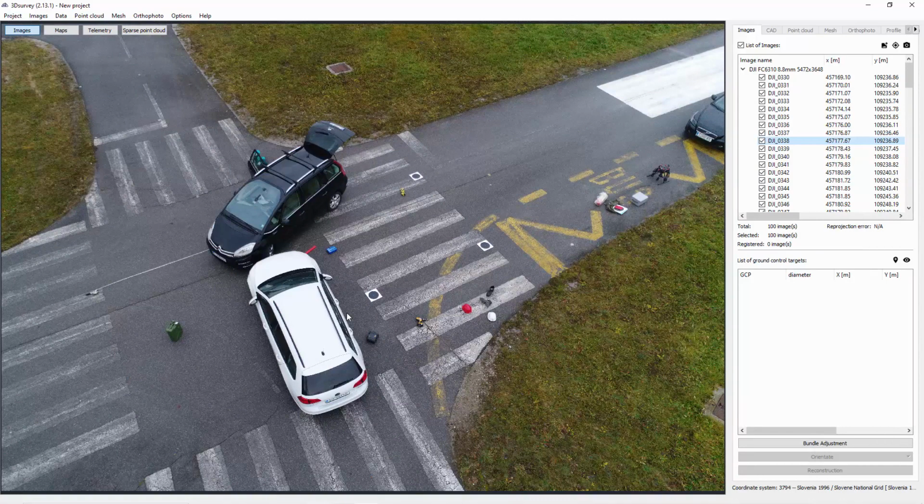about the orientation. Now here is a nice image where you can see three 3D Survey targets which were placed perpendicular to each other, and the distance between them was 3 meters. In this way we generate a so-called local coordinate system, and we generate our ground control point file with the local coordinates. In this case, we don't need GNSS instruments or GPS instruments, which can be quite expensive, from 5 to 10,000 euros. With this approach, we eliminate these costs. More police patrols can have that kind of system, so you need then just a drone, additional knowledge how to orientate it without measuring with a GNSS device, and it also works.